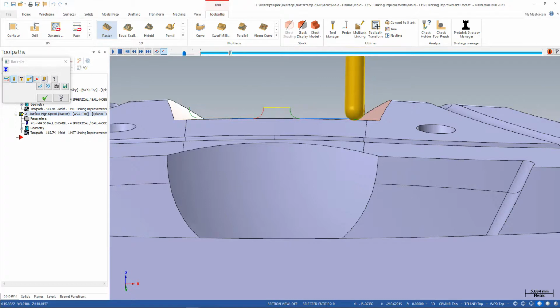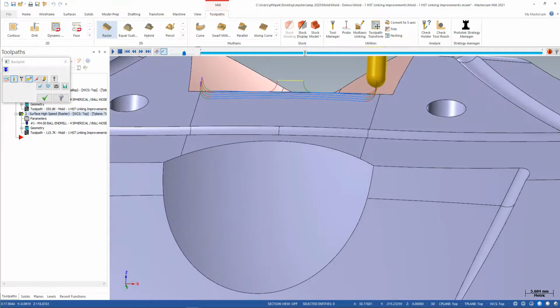So it'll work the same process back and forth. It's just going to trim the tool path essentially back for you so it doesn't gouge on its lead in and lead outs there. So it's smart enough to know that, and it's a pretty cool option that we never had. In the old parallel tool path, we were able to extend, tangential extensions, but now we can do it in our high-speed tool paths, and they work in all of them.